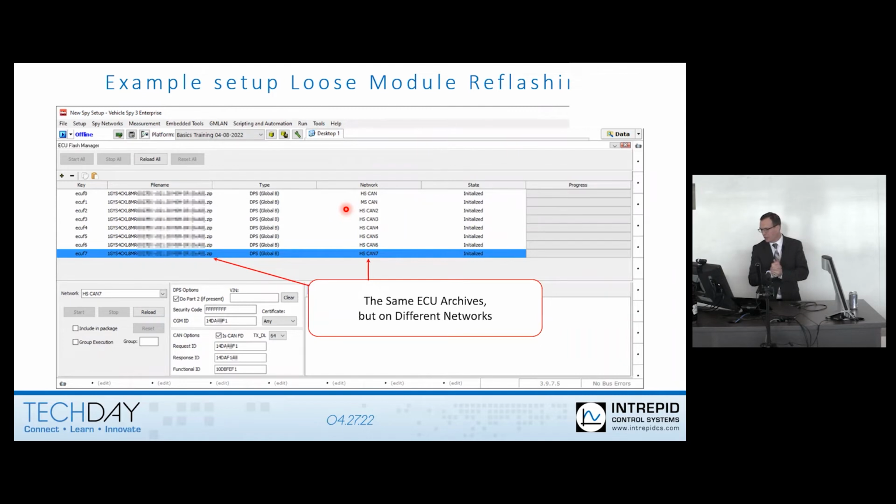Now you'll also notice here, this is where we have the configuration screen. This is where we set up the ECU addresses, whether you want to flash on CAN FD or not, and what your transmit data length is, in this case standard use like FD with 64-byte payloads.